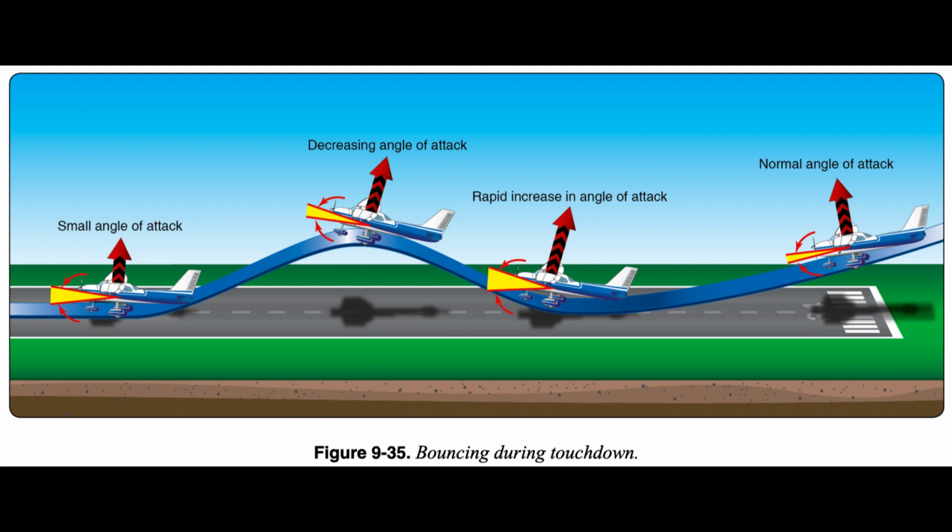Apply full power while simultaneously maintaining directional control and lowering the nose to a safe climb attitude. The go-around procedure should be continued even though the airplane may descend and another bounce may be encountered. Landing from a bad bounce should not be attempted, since airspeed diminishes very rapidly in the nose-high attitude, and a stall may occur before a subsequent touchdown can be made.